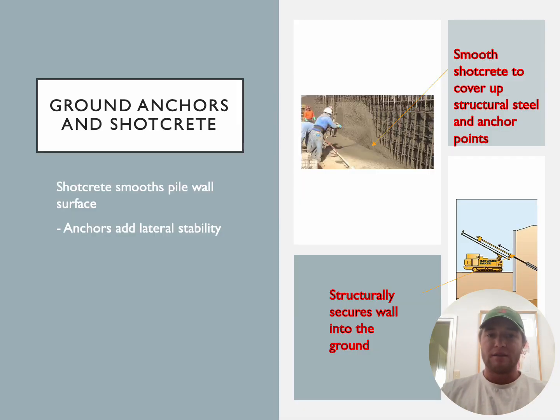Once retaining walls are in place, lateral earth pressure is countered using ground anchors. These are inserted into drilled holes and grouted before tensioning. Shotcrete is often applied to the wall face for a smooth and sealed finish. The interaction of shotcrete and anchor system allows deeper, safer excavations while maintaining soil integrity.